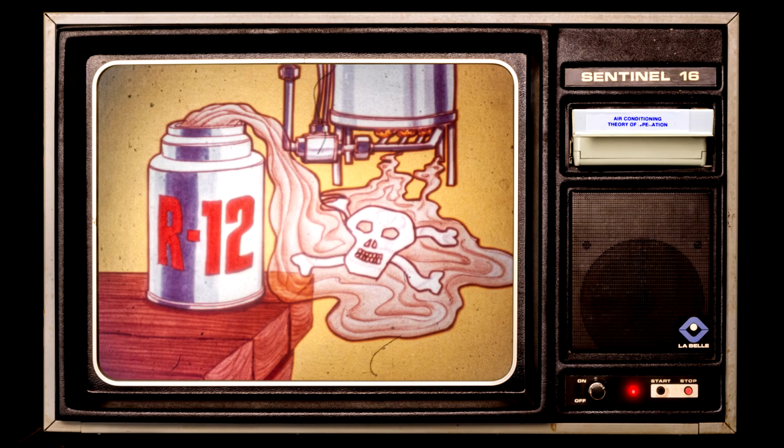Here's another potential hazard. When R12 vapors contact an open flame, a poisonous gas is formed. This gas, known as phosgene or mustard gas, was a lethal weapon used in World War I.